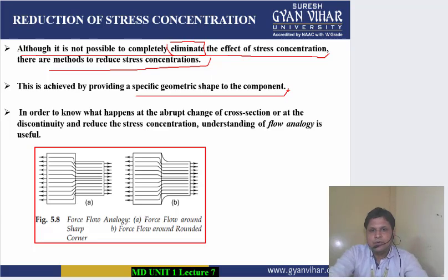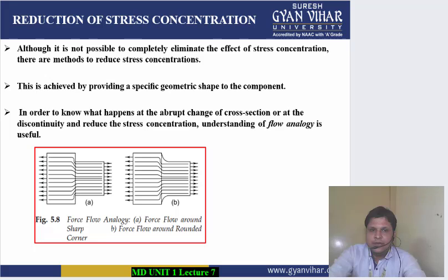In order to understand what happens at an abrupt change of cross section or at a discontinuity, and how to reduce the stress concentration, you can see the figure. In this figure, we have made a flow analogy between the flow phenomena and the stress phenomena. Through that we can understand what the problem is.